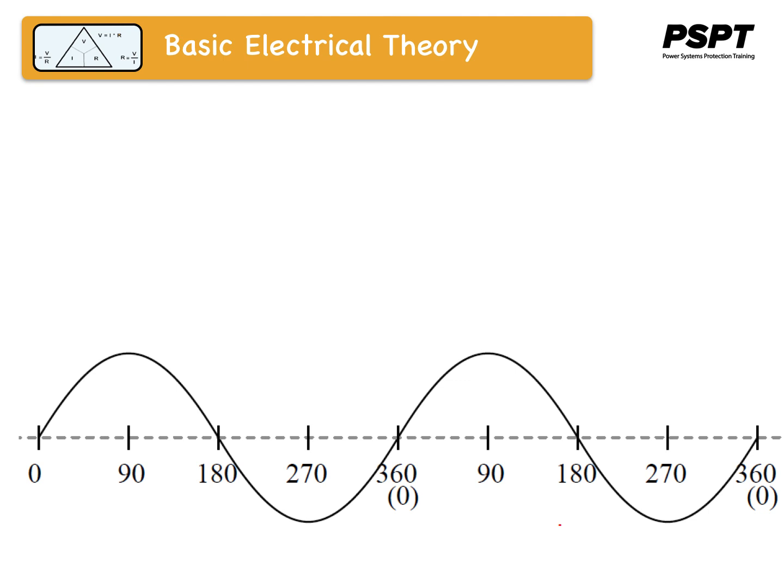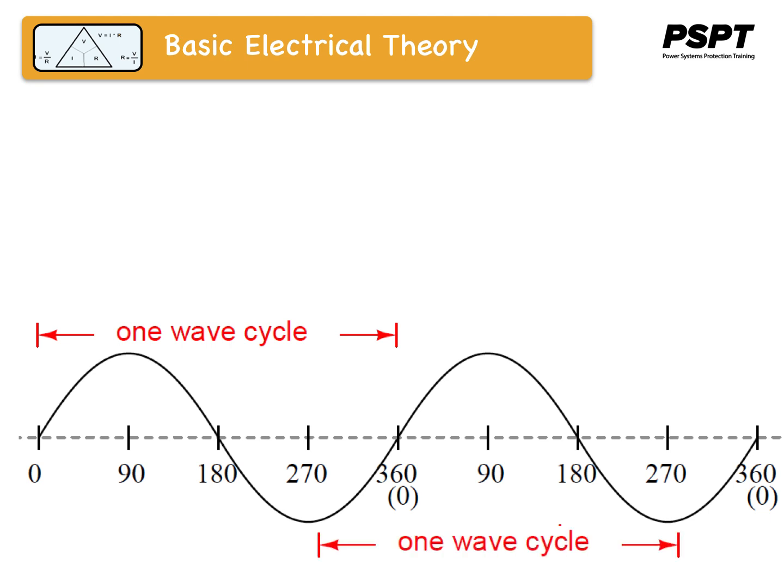If we were to follow the changing voltage produced by a coil in an alternator from any point on the wave graph to that point when the wave shape begins to repeat itself, we would have marked exactly one cycle of that wave. This is most easily shown by spanning the distances between identical peaks, but may be measured between any corresponding points on the graph.